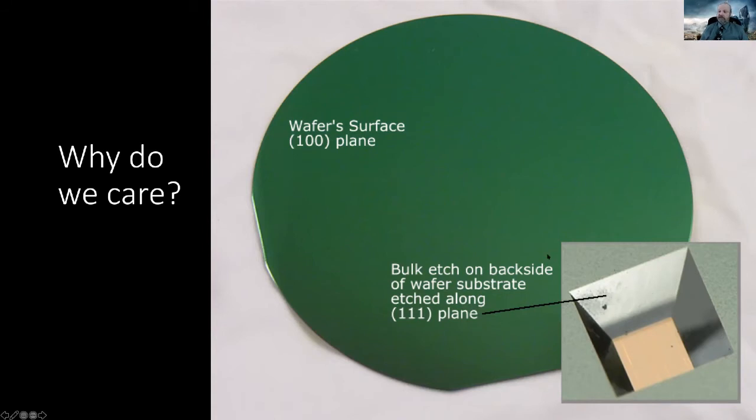Okay, but it tends to dissolve the 100 plane. It etches that much faster than the 111 plane. So you can see the sides of this hole that we etched are very smooth and haven't etched away. And that's the 111 plane. And then on the bottom, okay, you have the 100 plane, which etches really fast. And it kept etching until it reached the silicon nitride membrane on the other side.